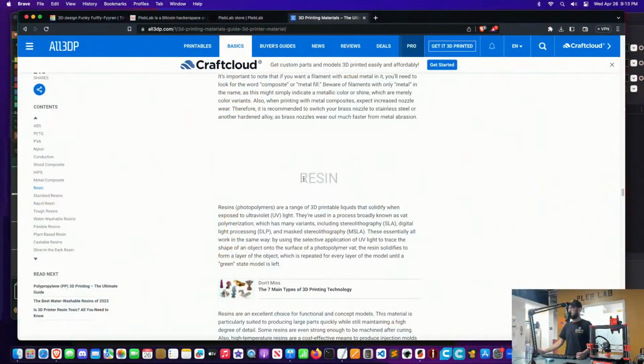Resin as well. You see liquid 3D printers. Nothing that looks like this. It's just kind of a box with a translucent colored lid for your UV light. It is essentially the same thing. Just invert this entire thing upside down and remove the tool head. The build plate is on top and the liquid is on the bottom, and it moves up 2, down 1. What that means is it's touching the liquid, it flashes the light or moves the laser, it draws your geometry, again, same thing, layer by layer, and it moves up 2 sections to go up 1, lets the excess material roll off, and then it drops back down for that additional layer. And then you just build it from there.